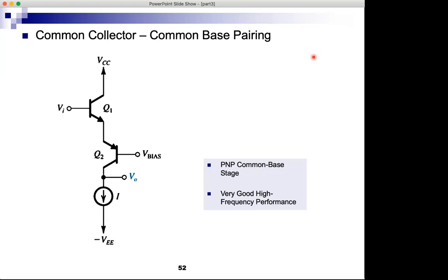is that the direct connection here allows the same current to flow. If we assume that the base current is small enough, I have the same bias current flowing in the two transistors, and just one current source is enough to bias the NPN and the PNP. If I want to use two NPN, I may need to use two current sources to bias them separately.